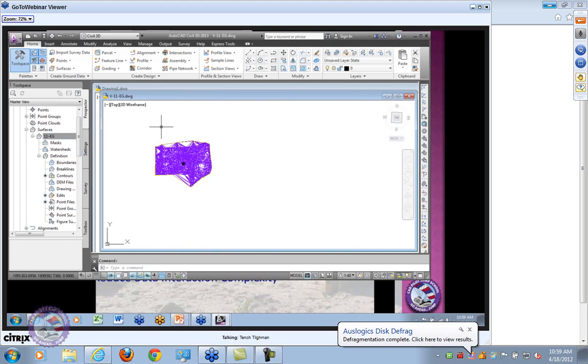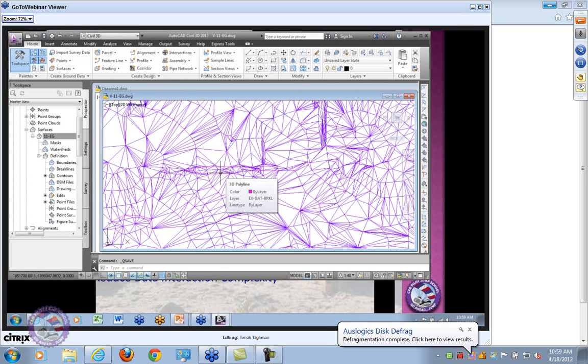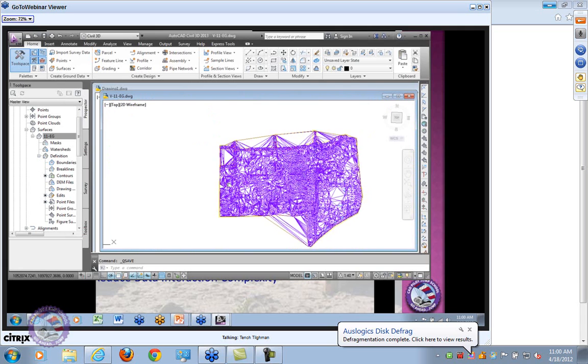By the way, if you want to keep your Civil 3D, you probably want to do a save here. Okay, AutoCAD Civil 3D actually employs the real AutoCAD objects to process once they enter the surface model that way. So break lines work this way, contours work this way. My point files are an external source, but the contours and all those kinds of other data employ real AutoCAD stuff. So getting them in the right place, keeping them there, and making sure people don't just inadvertently erase stuff has got to be part of your QA process.